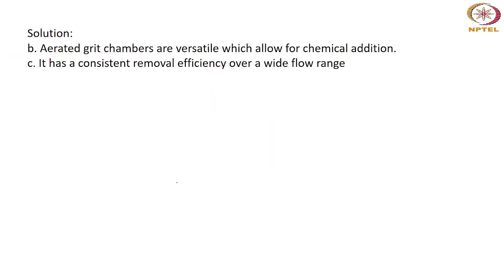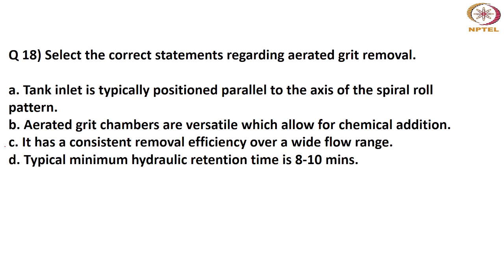We'll go for the solution. So B and C are the correct ones. Aerated grit chambers are versatile, which allows chemical addition. You can add chemicals, maybe for the purpose of coagulation, or it has a consistent removal efficiency over a wide flow range. So those are the two correct statements. These others are not true.